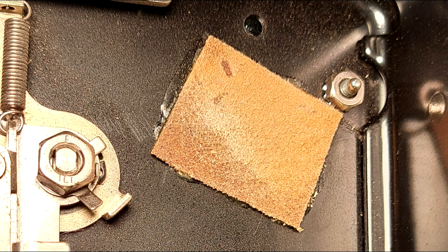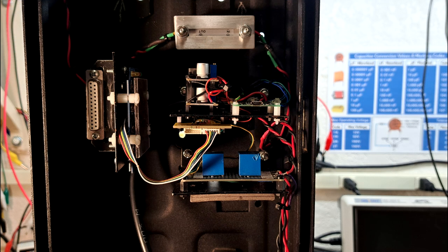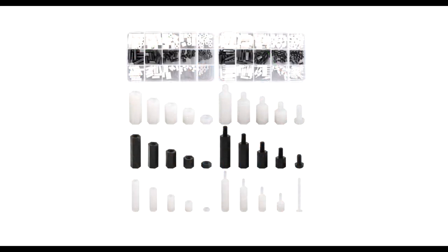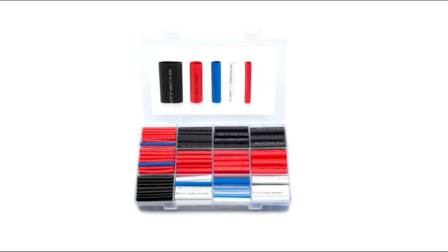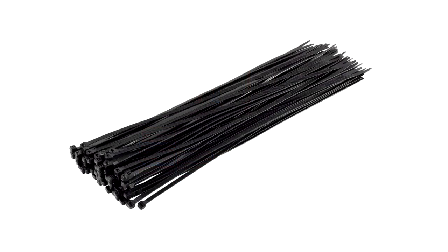a coin is deposited. When all modifications and connections are completed and the system has been tested, you will want to neatly mount the components inside the phone. Use insulators such as nylon posts or standoffs so that nothing touches anything it shouldn't. Using shrink tubing on connectors is advisable. Use zip ties to neatly and safely secure the wiring.